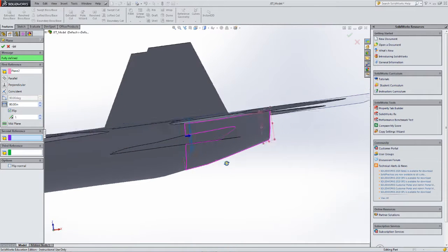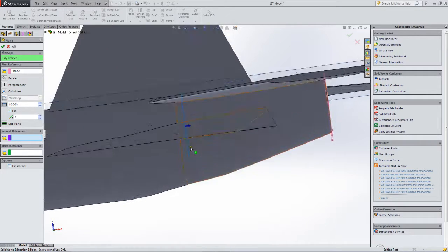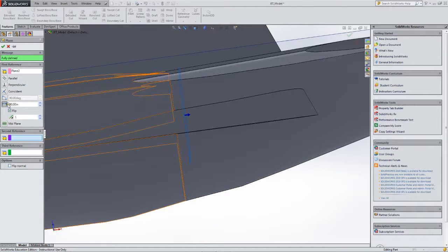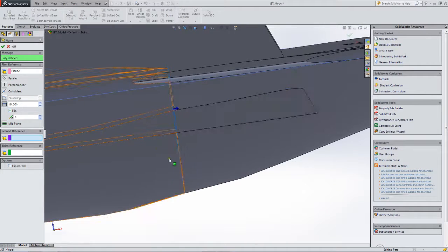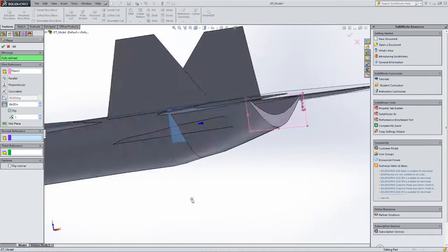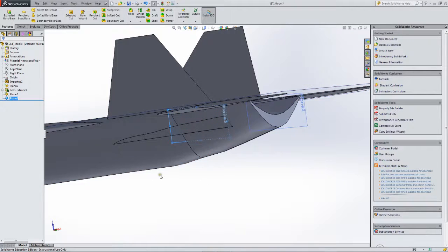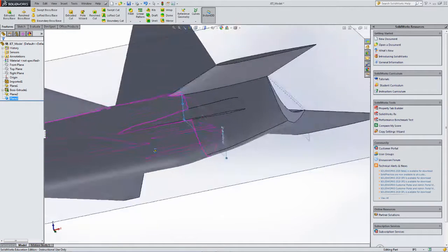We could look on Jet because this is a specific fuselage frame in Jet. Let's try 90. Ooh, let's try 84. That's good enough. That's probably just right. Okay, so 84. Okay, and then green checkbox. Like I say, sometimes when you click somewhere else it exits anyhow.